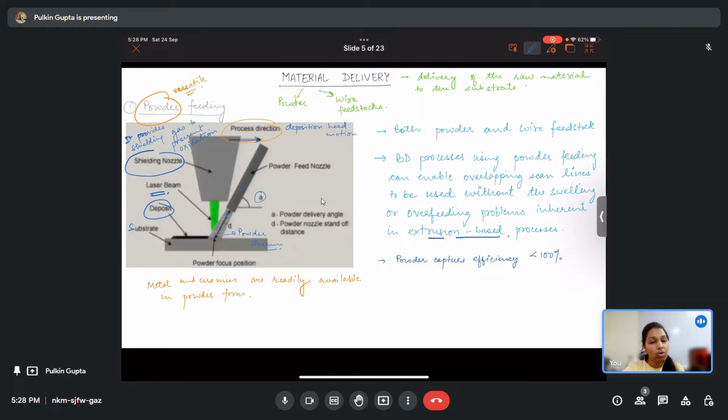Okay, so now care must be taken that initially you provide some excess powder so that there is no shortage of powder. So excess powder is fed, and care must also be taken that whatever excess powder is being fed, that is taken out without any loss or degradation if you are to recycle that powder. Okay, so that excess powder should be recaptured in a clean state.